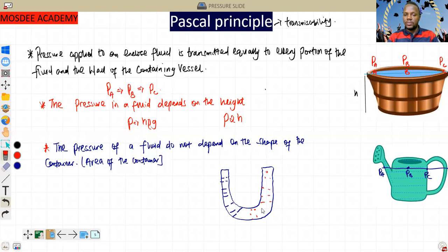As in, I have different liquids inside this now. So if I draw a straight line, which is our horizontal line that we've discussed here, the pressure at this point A, and the pressure here, we call it the pressure at point B. You should always keep it in mind that the pressure at A is not equal to the pressure at B. And the reason is because there are different liquids inside this vessel.